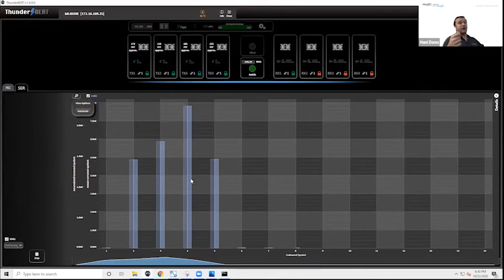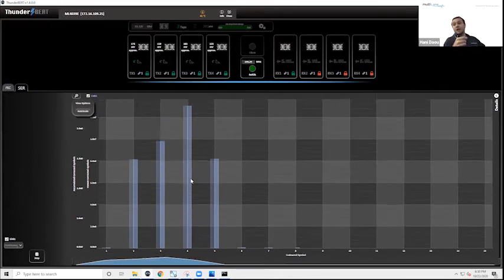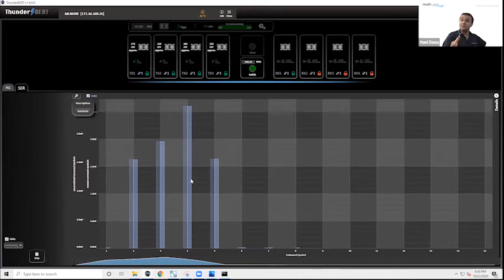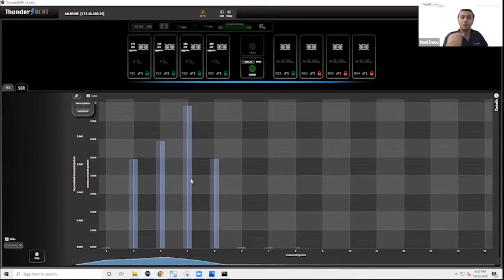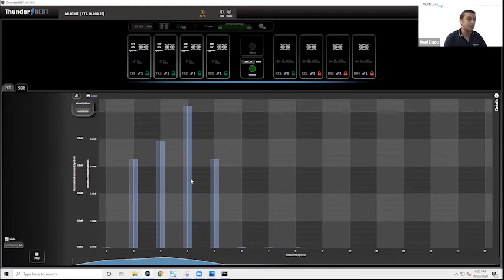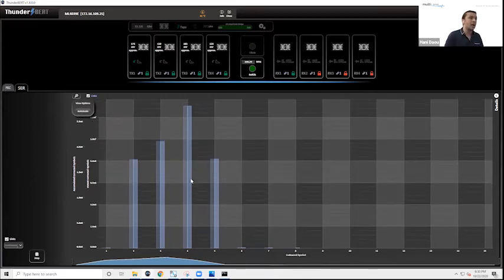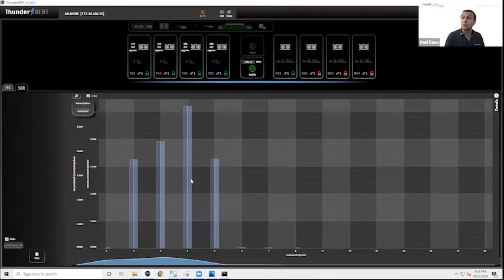In fact, pre-FEC bit error rate can be up to around 2 times 10 to the minus 4 before the post-FEC bit error rate becomes uncorrectable. So with our SER, with our real-time corrected bit counts, corrected code word, and uncorrected code word counts, we have full hardware FEC, which we are proud to introduce to the market effective today.